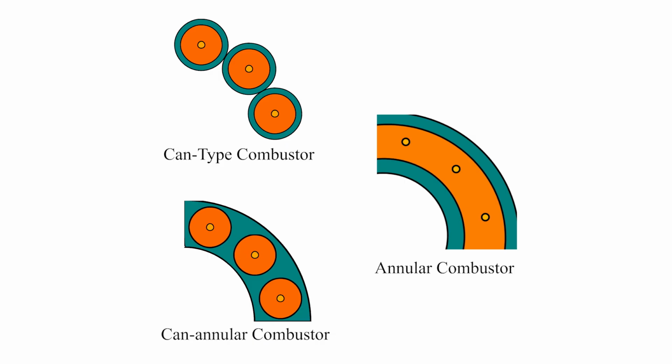Carbon monoxide is an intermediate product of combustion, and it is eliminated by oxidation. CO and OH react to form CO2 and H. This process, which consumes the CO, requires a relatively long time, high temperatures, and high pressures. This fact means that a low CO combustor has a long residence time, which is essentially the amount of time the gases are in the combustion chamber.